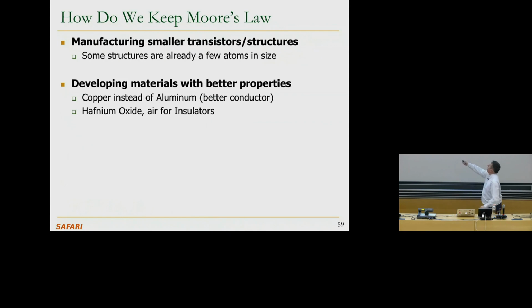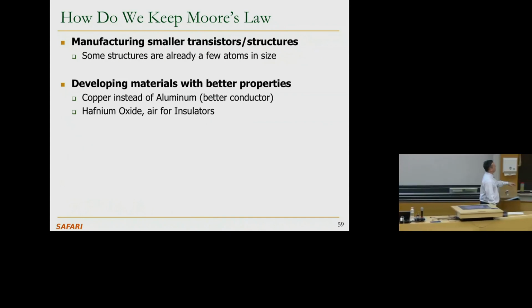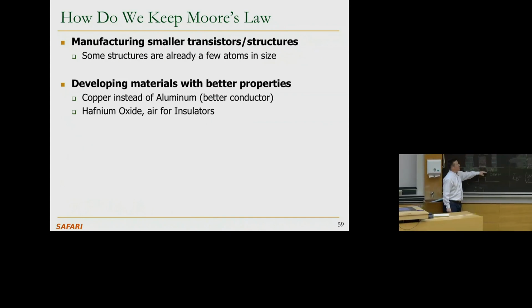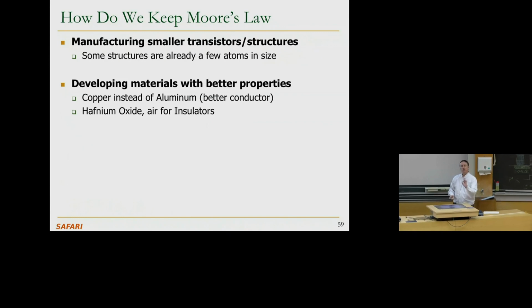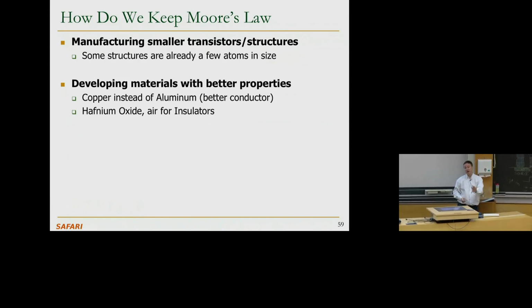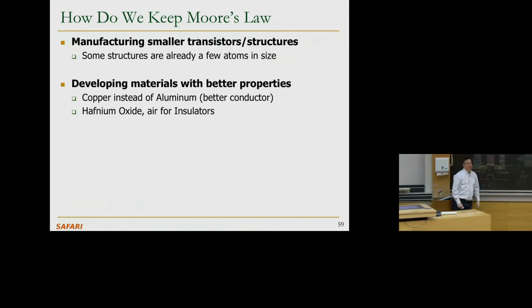There you go, hafnium oxide. We actually started with silicon dioxide. Why? Because the bottom material was silicon. To get silicon dioxide out of silicon is very simple. You literally rust silicon. You heat silicon to 1,000 degrees, you introduce some oxygen, and that oxygen combines with the silicon and forms silicon dioxide. You can control this process very finely and say, I'll cook this at 1,052 degrees for 42 minutes, and I'll have 42 nanometers of oxide nicely produced here.